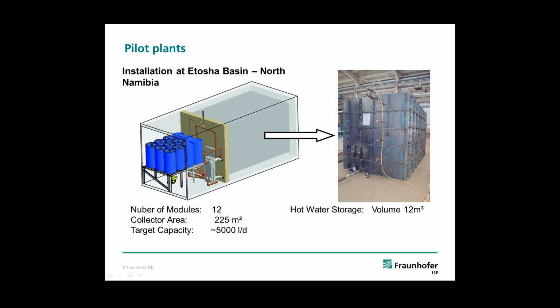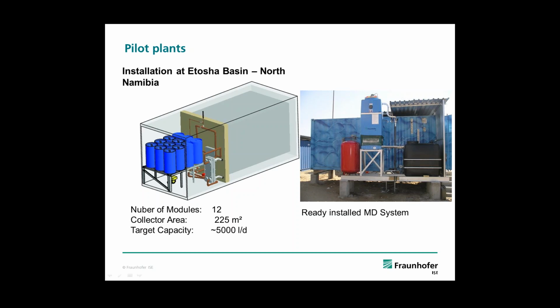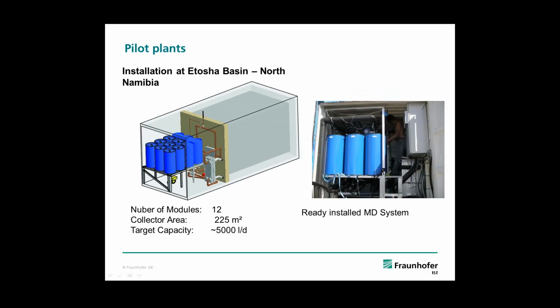So different module configurations exist. At Fraunhofer, we mainly design spiral wound configurations with about 10 to 14 square meters of membrane area, but we also have plate and frame modules, so both configurations are possible. In the institute we have a device to produce the spiral wound modules. You see a winding machine on the left hand side. There are all the different materials, membranes, spacers, condenser sheets, which are wound together here. And we also have small plate and frame modules together with our spin-off company, Solar Spring.